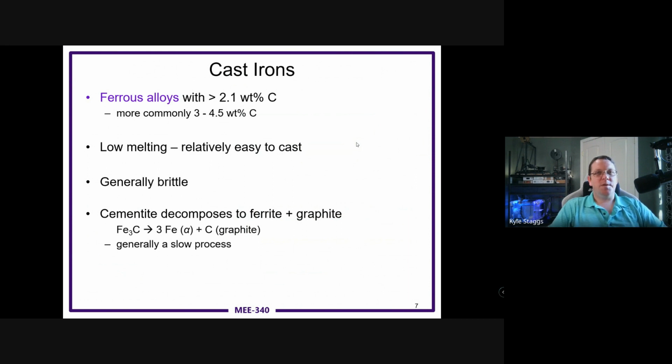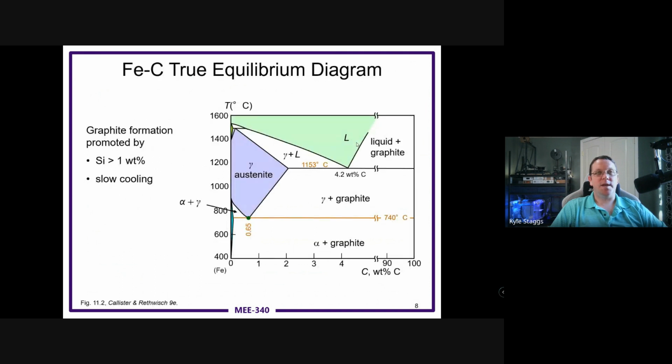Most of these are going to be iron carbide. There's going to be a lot less of the alpha iron, but there is also going to be a lot of just graphite, just carbon together. So those things deposit in a couple different ways, and that's generally pretty slow. So there's a slow cooling that happens, again, to conserve the energy of manufacturing for the sake of simplicity.